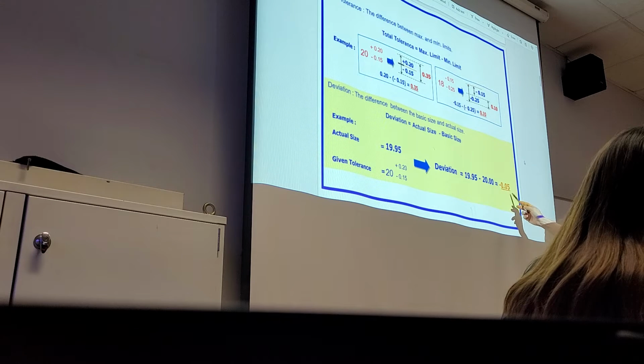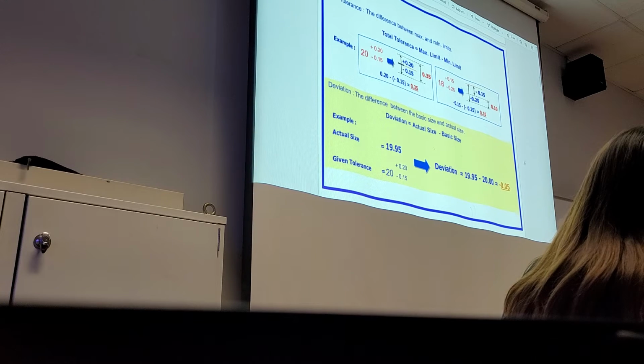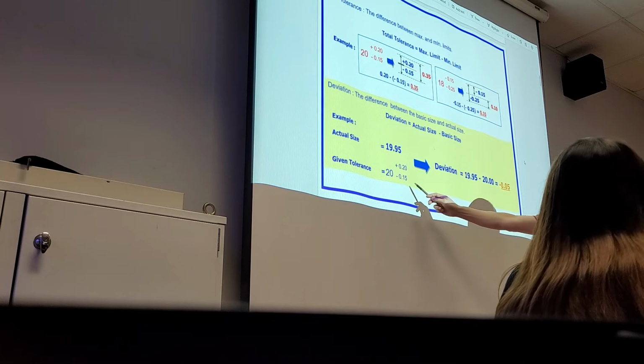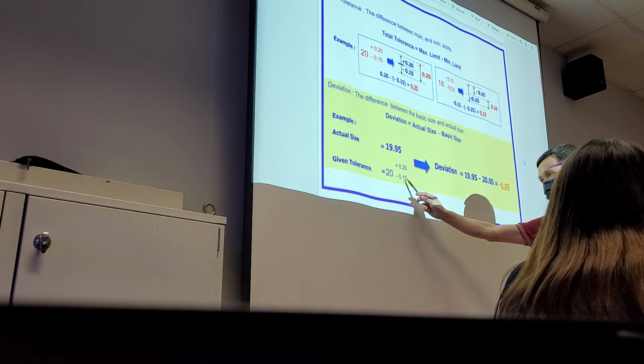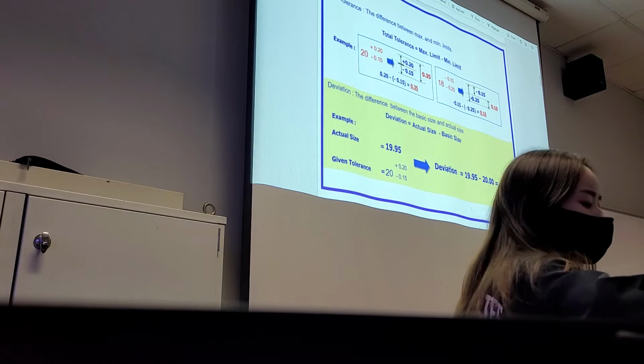That's the QC job, because the QC needs to check and see your actual work pieces. You pick it up and then measure. It's a minus 0.05 difference, and I allow you minus 0.15. Okay, good. So this one is acceptable.